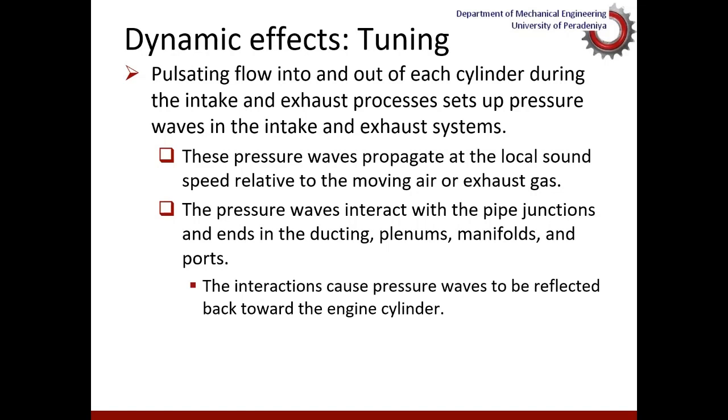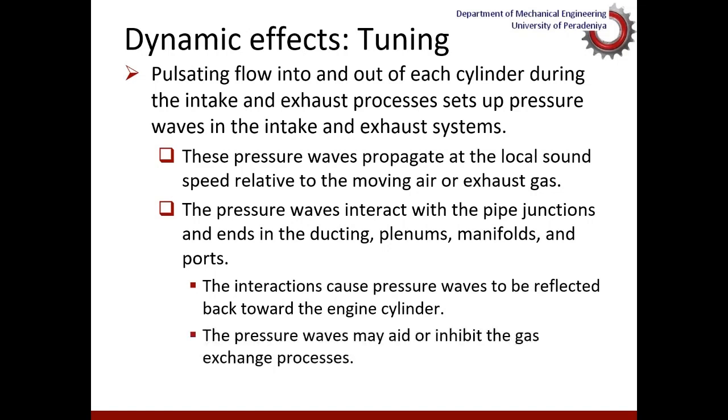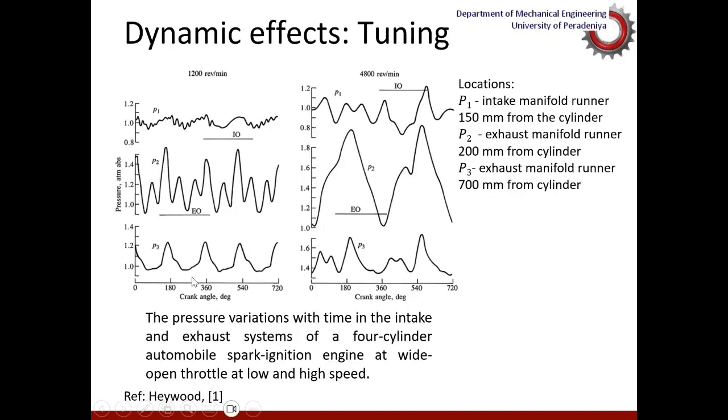As a result of these pressure waves going out, for example, from the cylinder and hitting the walls of the intake system, it will reflect back, and that reflection would drag more air into the cylinder. So that is called tuning effect. You can see this variation of pressure against the crank angle in the intake system as well as exhaust system at different speeds.